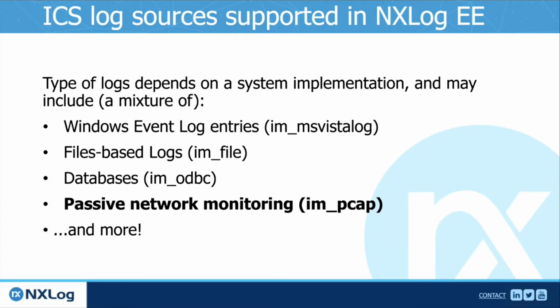Due to this enormous diversity, typically SCADA or ICS system implementation consists of a very specific mixture of different logs. So from the most important, we should probably include Windows event log entries. Still, Windows is the major system which controls the ICS systems. We can distinguish also file-based logs.